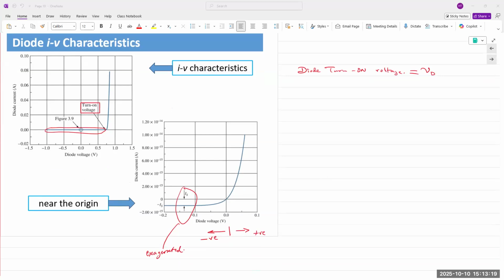Okay. All right. So IV characteristics, we were talking about how the diode is a nonlinear device. Once we apply a diode biasing voltage across its terminals, it does not turn on because there is a junction barrier in between, known as the depletion region. As the voltage increases, carriers are pushed towards the junction, so they're able to cross over. Slowly and steadily, the current starts increasing when the voltage is increased.